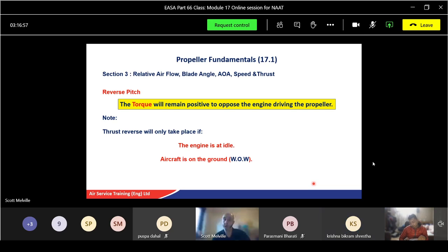Well, weight on wheel. It's a micro switch. When your undercarriage comes down, as the aircraft weight goes on the undercarriage, it will engage a micro switch. That will allow you to select reverse thrust and many other systems in the aircraft that are only activated, or in fact disengaged, when that switch is engaged. So it's a weight on wheel switch.